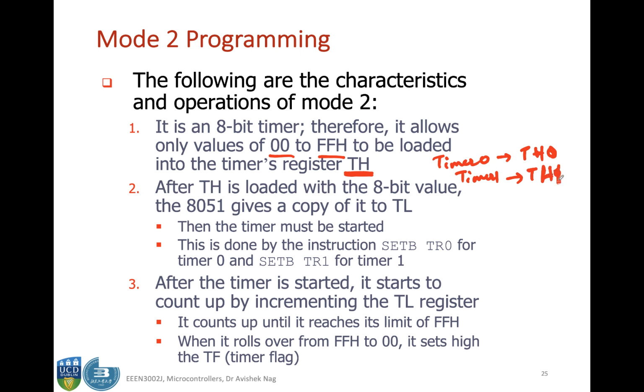So you load an 8-bit value to the TH registers of the corresponding timers with which you want to work. So after the TH register is loaded with the 8-bit value, the 8051 gives a copy of it to TL, okay. Then the timer must be started.